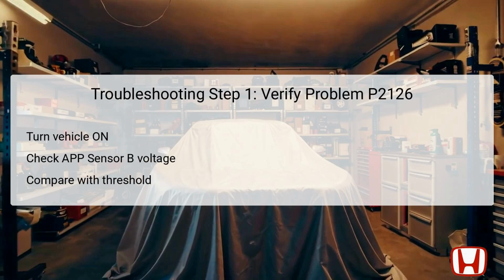The first step in troubleshooting the P2126 fault is to verify the problem through direct measurements. Begin by turning the vehicle to the on mode, ensuring that all electrical systems are activated. Utilizing the HDS Honda Diagnostics system, monitor the voltage levels from APP sensor B. The current conditions should then be compared against the specified thresholds, where readings should ideally be less than 0.19 volts or higher than 2.62 volts.